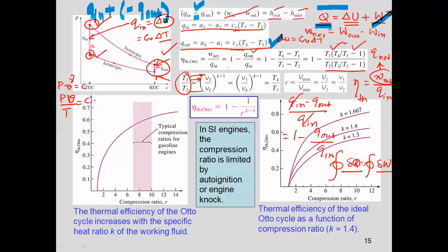So that is a property. That is the equation of state. So if we apply these two, then you will be able to get, you see that in the process equation, there is no temperature, but here we have temperature. So we will try to replace this PV relation in terms of temperature by using these two, and we will be finally able to get the temperature ratio in terms of volume ratio.